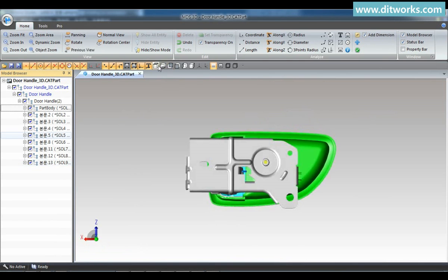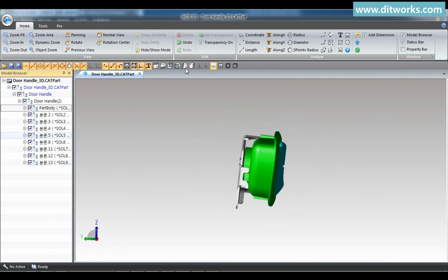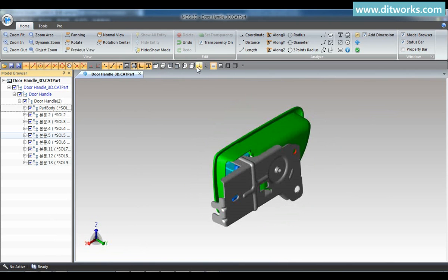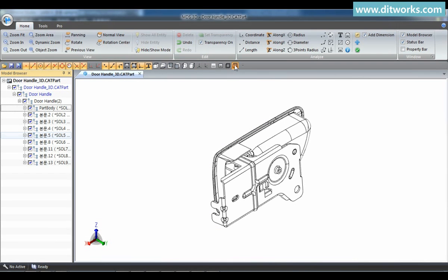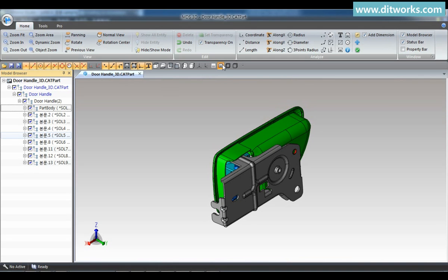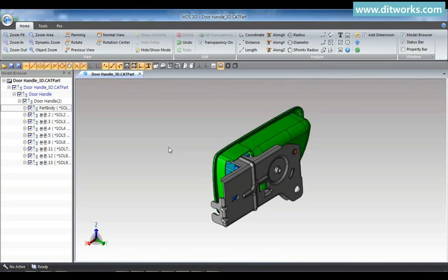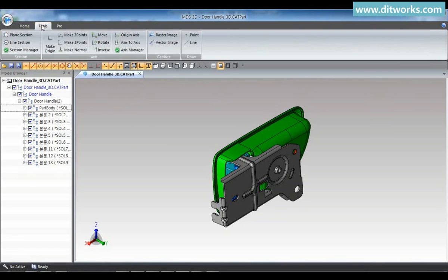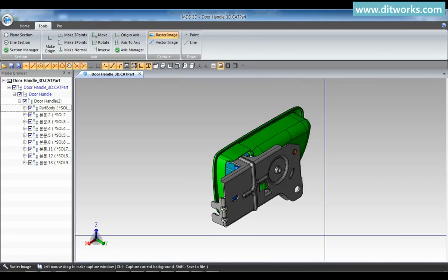You can see the ISO view, Southeast ISO view, and front view of the shape with the view icon, and wireframe status, hidden line removal, and shading status including edge line, shape reflection and shadow effect. You can also see them selectively. In a shape with many assembled parts, select the part that you want. Copy the image, and various forms can be utilized in the document.